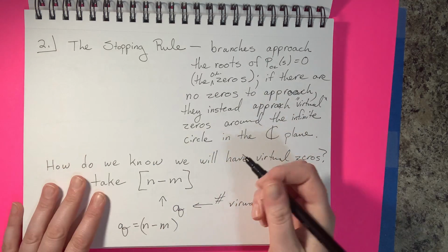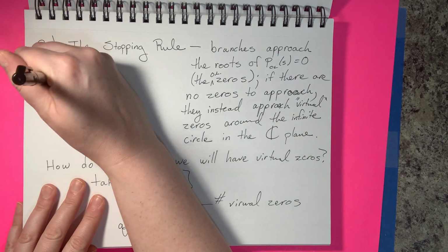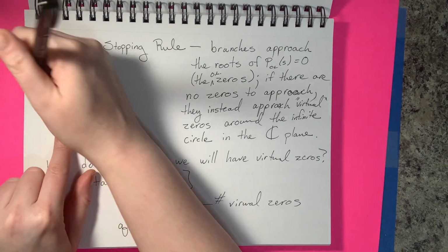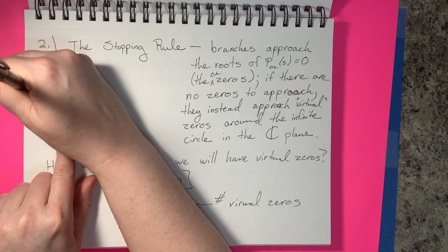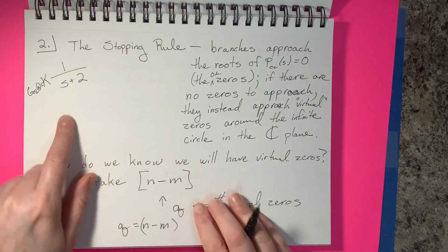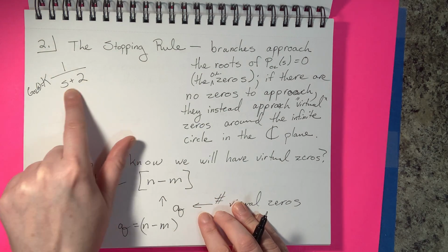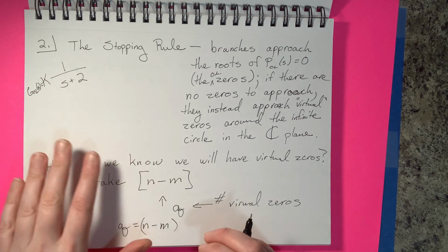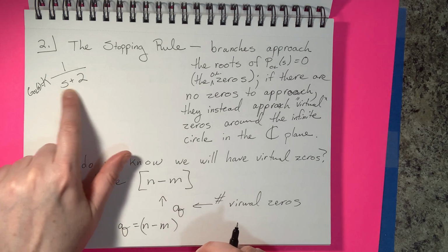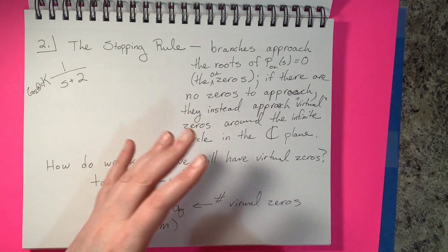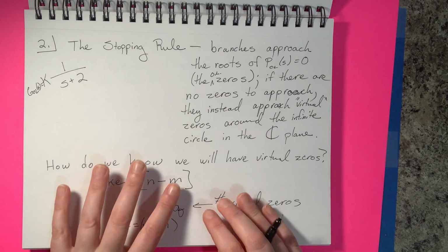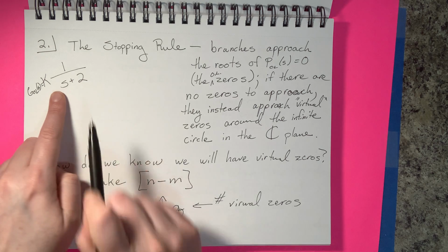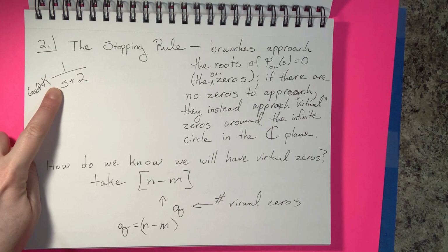But as you've noticed many times, there is, say, a case like this. Of course, we've got our K out here, but in this example, I have a pole down here, but I don't have a zero. There is no zero in this case. Okay, so in that case, this pole would be migrating towards a virtual zero. And we can figure out how many there are. I know that the order of the polynomial in the denominator is 1.